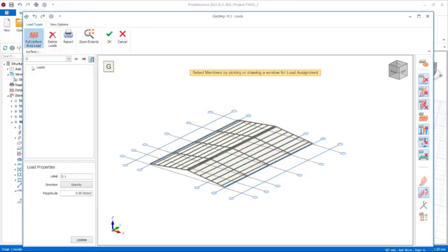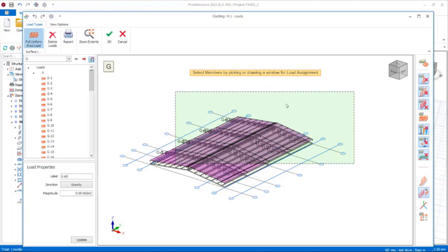Once you click on that, we will have to identify the load we are going to be applying. This is the dead load, which is the G. And if you click in this drop down, we also have the Q, which is live load, and as well the wind load. But in this lesson, I will show us how we can just apply the two loads, the G and the Q successfully. So you have to select all of this again, just like this.